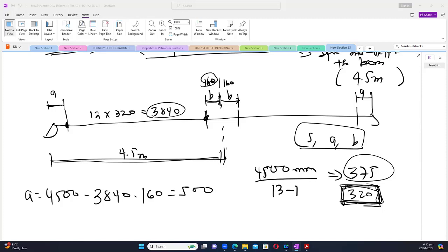So that you can connect the steel and the concrete so that they become one unit. And when you do that, we have something called a full composite action, where we will be able to reach our design moment, which was 601 kilonewton. We don't want the thing to fail in shear, so we have to get up to that capacity it can hold. We want to utilize that full capacity. But we can utilize it only when the concrete and the steel section do not slip. When there is significant slip, they don't act as one unit, so it's like the concrete is separated from the steel.